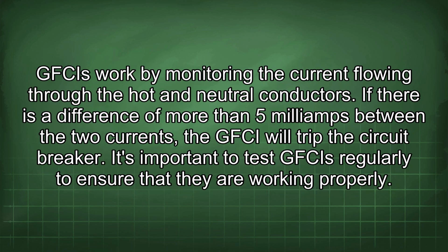GFCIs work by monitoring the current flowing through the hot and neutral conductors. If there is a difference of more than 5 mA between the two currents, the GFCI will trip the circuit breaker. It's important to test GFCIs regularly to ensure that they are working properly.